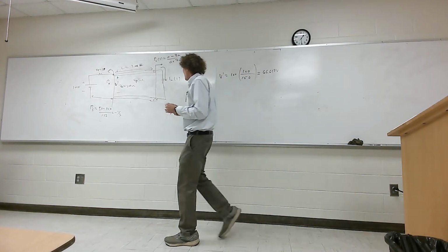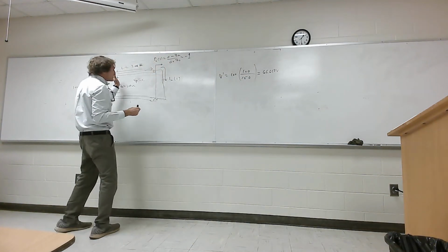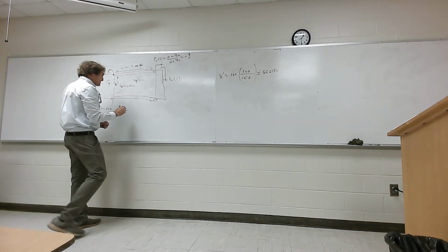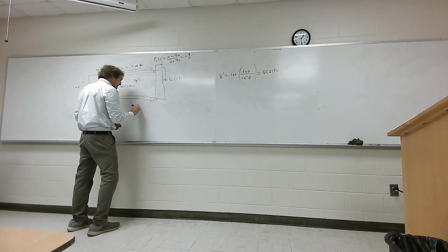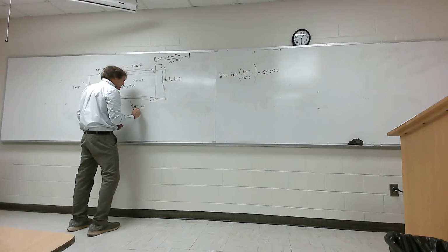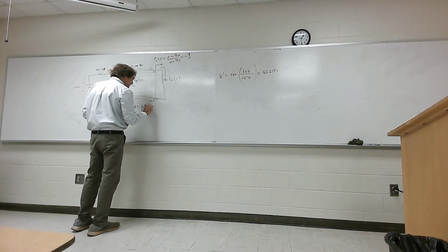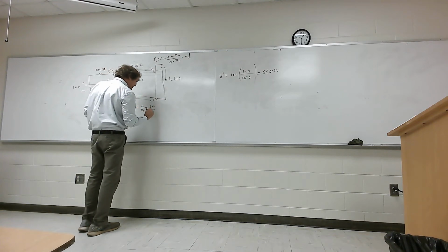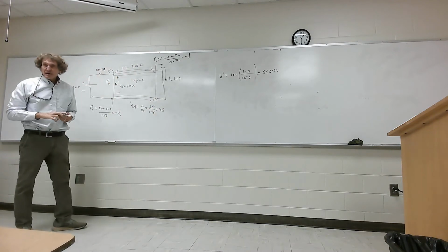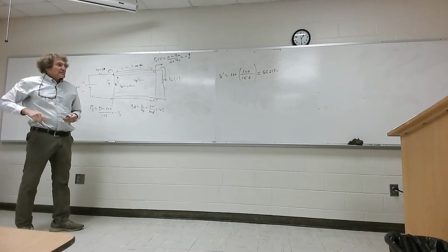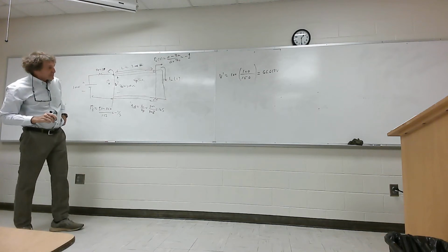Everybody with me? Now, it's going to take, did I get the time? No, I didn't. So the time delay is what? That's going to be L over V phase, or 300 divided by 3 times 10 to the 8, and that's 1 microsecond, isn't it? Correct, class? So then after that, what happens?